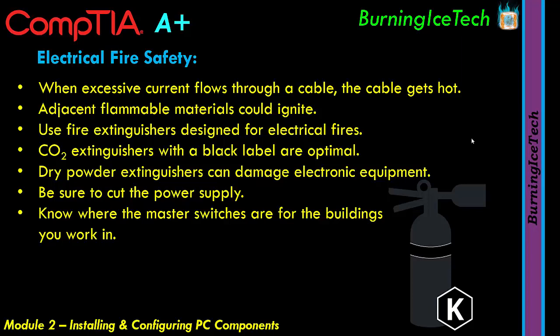Obviously, if you have an electrical fire, which is the most common scenario in IT, you don't want to use water on that, or some sort of liquid-based fire extinguisher. That's a bad idea because, as we've said earlier, liquid is a conductor. So if you've got an electrical fire, water or liquid is the last thing you want to find yourself using. You're probably going to end up using CO2, carbon dioxide, I think is what they call it. Oh yeah, they mention it on point 4. CO2 extinguishers with a black label are optimal. That's perfect for electrical fires.